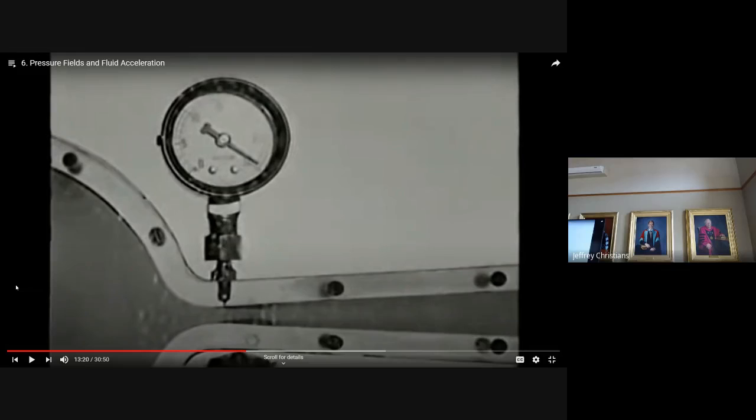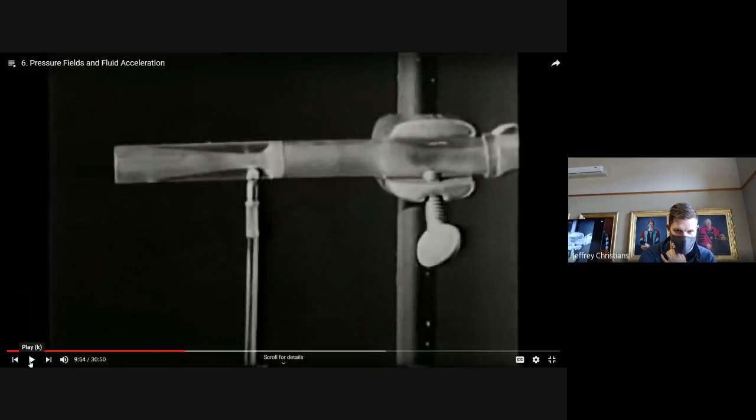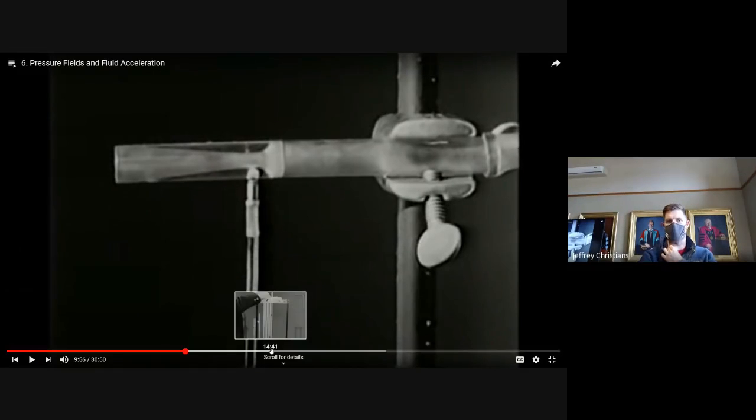So this I'm kind of assuming is, let me go back to this. This is really the system that we're looking at. So he's blowing air from right to left. It's discharging out here at atmospheric pressure and it's causing a suction down at this end, where he's sucking liquid up that straw.